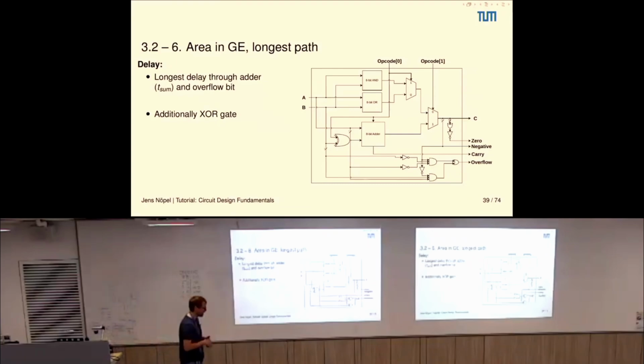The idea behind gate equivalence is that you make different technologies comparable. Let's imagine you have different vendors of your chip technologies, and they all provide you with different gates, right? But they are all going to provide you with the same logic functionalities.